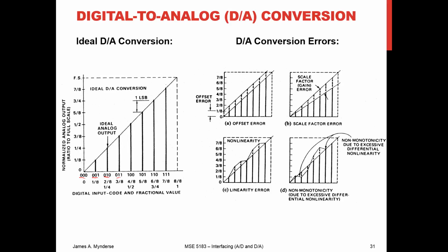And essentially, in this case, we're talking about fractions: 0, an eighth, all the way up to 8/8, which would be a full value. So this is something we can scale for 8 different values, which would be 3 bits. We could scale this across anything we wanted. If our reference voltage was 10, we could have 1/8 times 10 volts, and so forth.